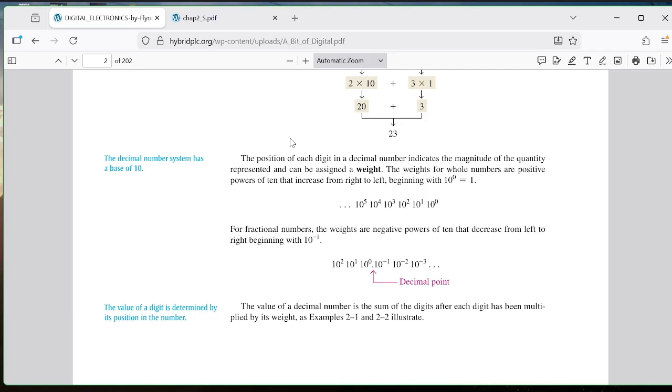It will be one or the other, or it can be both at the same time, 16 bits or a number. Sometimes it's 16 bits, sometimes it's a number. It can be flipping back and forth, and you can be doing both at the same time. So I want you to get that, 32-bit, how that's done and all that kind of thing, because in PLCs we're dealing with numbers a lot, and we're also dealing with Boolean logic. The ability to flip back and forth between the two, and sometimes use 16 bits as a number, sometimes use it as 16 control bits, is extremely important.